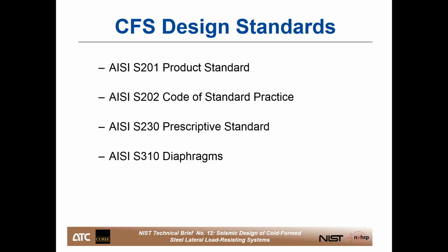S310 applies to horizontal and vertical diaphragms using profiled steel panels, and it provides the strength and the stiffness of the diaphragm membrane. It doesn't provide design of the full diaphragm system, so keep that in mind if you're turning to S310. All the information you would need to look at the diaphragm membrane and its connection to the structural members is in there, including strength and stiffness provisions, but it won't tell you, for example, how to design a collector, or chord forces and those sorts of things. So those you would refer back to, say, an S213 or an S400 for additional guidance.